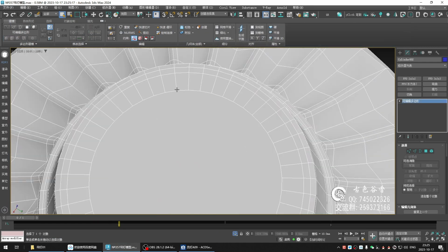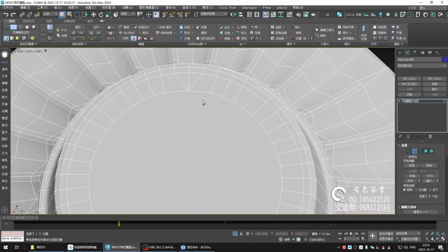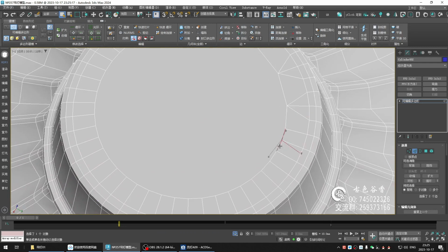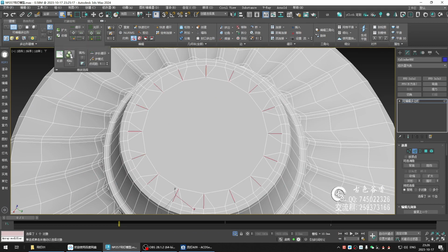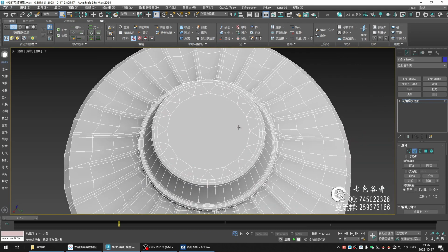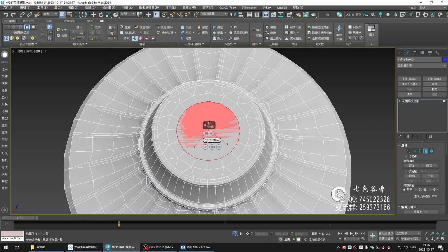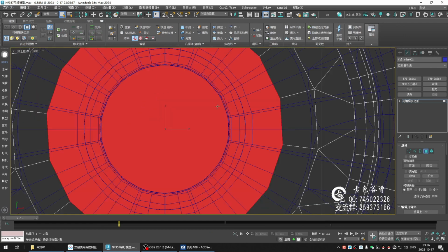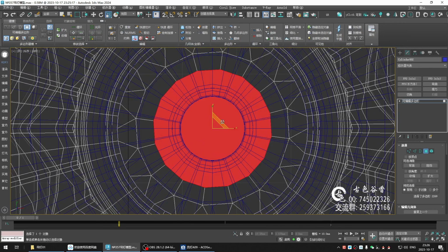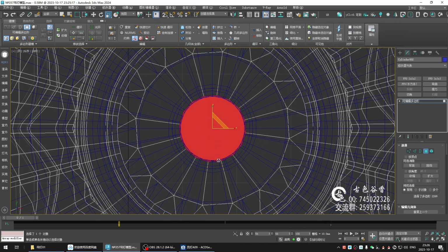And then we'll deal with it over here. Next side. Pick one after the other. It's gonna cave it in like this. And then choose this side. Similar selection. Press Ctrl plus backspace to remove it. Select this face and insert it. Zoom it in the top view. Go to this side here.